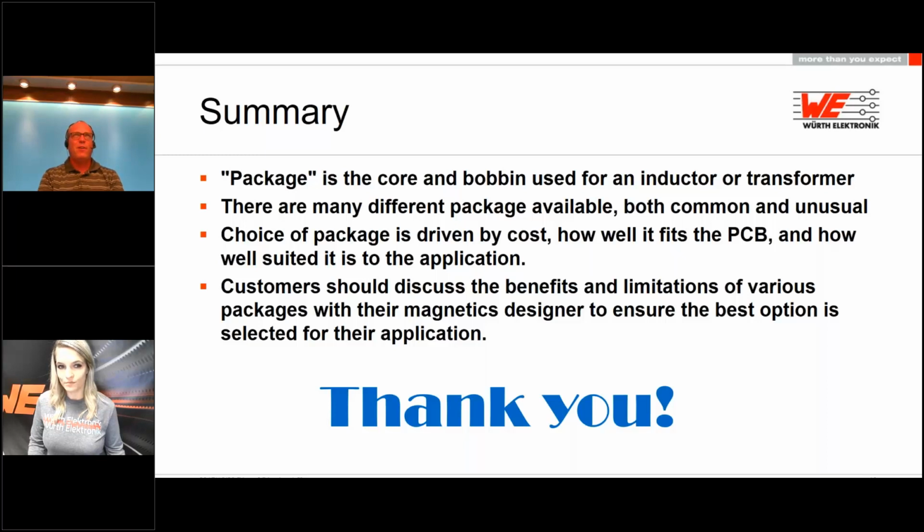Current, that's a good question about current and wire size. It was a little hard to tell on the scale of the pictures that I did, because of course they all look the same size. But if you see the packages next to each other, an EP package may have 2 millimeters between the pins and an ER package may have 5 millimeters between the pins. So if you're using applications that are 10, 15, 20 amps or more, and you need to put on 20 gauge wire or the equivalent size litz, in some cases it's not even physically going to fit on the smaller packages.